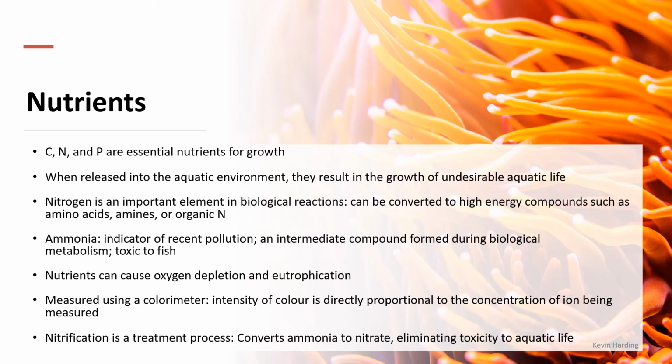Nutrients in the water are often needed for growth, particularly carbon, nitrogen, and phosphorus, but they can also be harmful and undesirable to aquatic life. Nitrogen is an important element in biological reactions, and it can be converted to amino acids, amines, and various other organic compounds, but we also have ammonia, which is an indicator of recent pollution, so that's the NH3. It is also an intermediate compound which can be formed during metabolism, and it is toxic to fish. The nutrients can also cause oxygen depletion, as well as eutrophication, which we will get to in another slide.